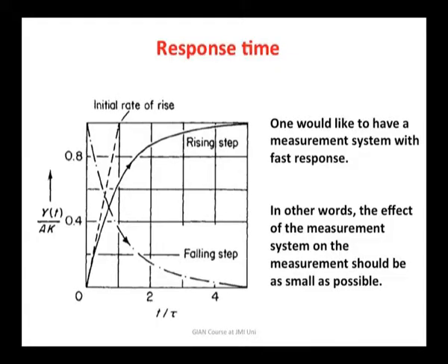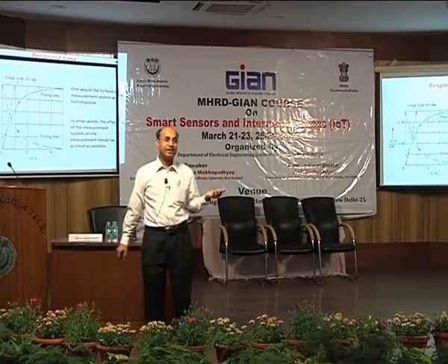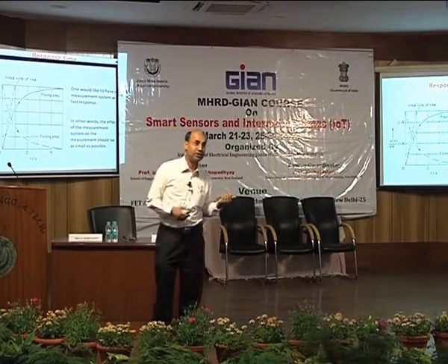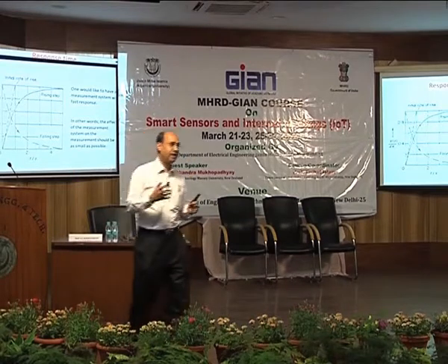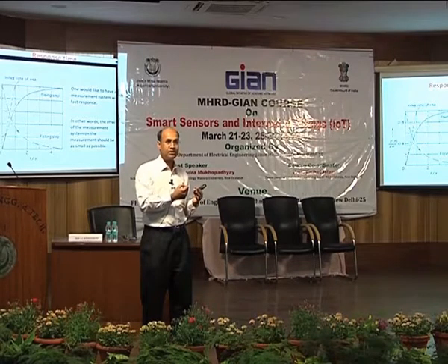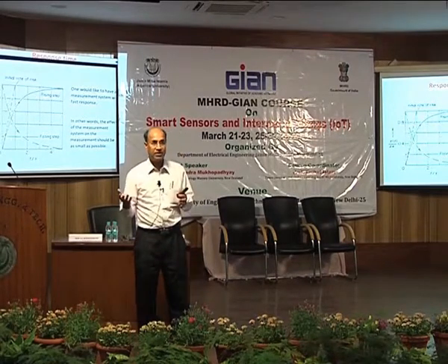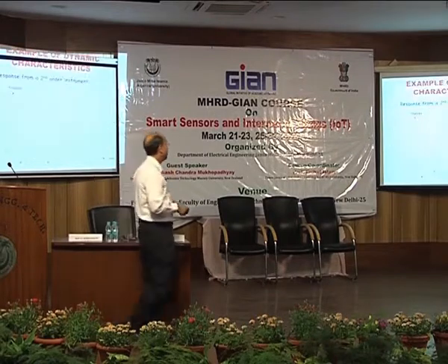So the first order system again is rarely what you get in life. Okay? If you get a first order system, you are really lucky. But you never get a first order system. Many times we make a second order system by giving too much damping to make it first order, but usually we don't have first order. If you have first order, you have only the rise time.